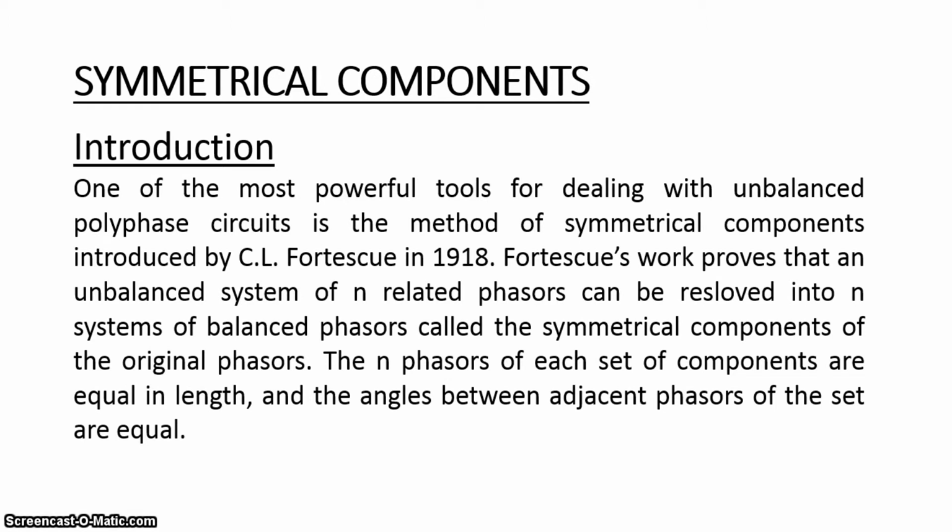Symmetrical components are nothing but sequence components. It is known that a balanced symmetrical three-phase system can be analyzed on a single-phase basis using a single-line diagram and reactance diagram, but an unbalanced three-phase system does not permit this application as it involves phasors of different magnitude and phase angles in each phase. A fault in the system can cause the system to become unbalanced. Analysis under unbalanced conditions can be carried out on a three-phase basis using Kirchhoff's laws, but this is a very difficult process.